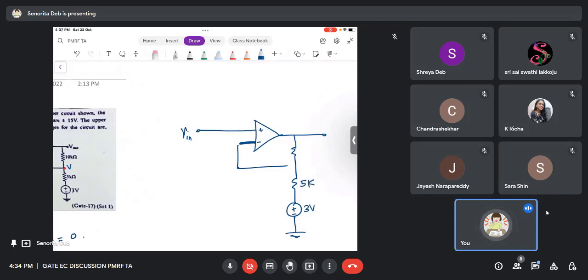So this is related to the topic of Schmitt trigger, which is a very important topic. You see here that this voltage V gets compared to Vin, and therefore now you actually have an upper threshold voltage and a lower threshold voltage. So we can write an equation for V. What will be the equation for V?